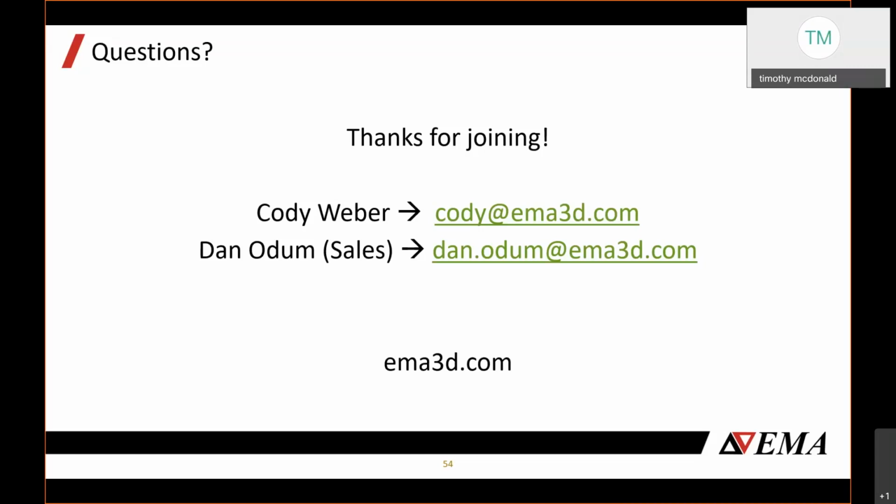That's a good question. When we're considering the terminations associated with our cables, we have different impedances that can be applied to the end. If you're talking about your L, R, or C values that might be associated with your LRU and your circuit terminations, those can be estimated and added. We do not have in these full wave simulations the ability to represent all the details of the LRU, but the front end characteristics are usually good enough for that.